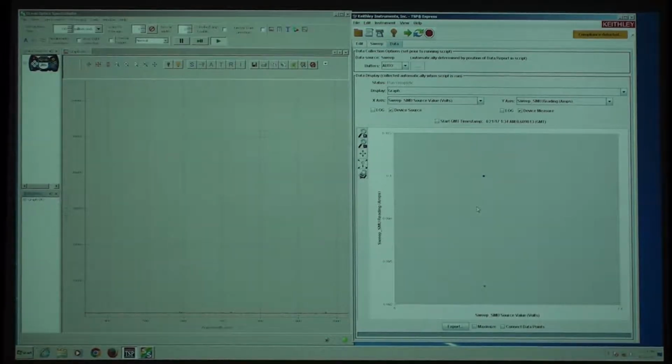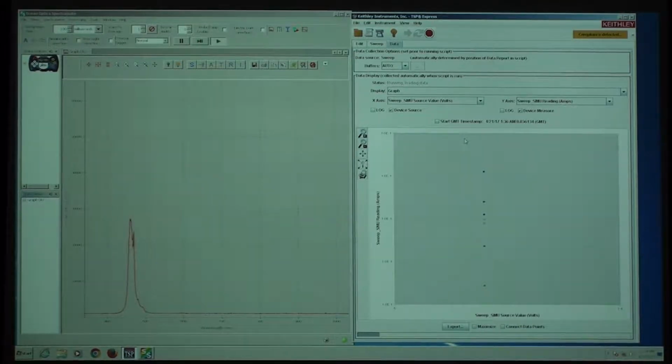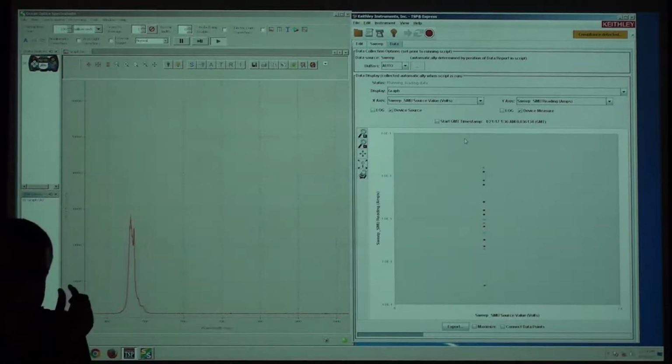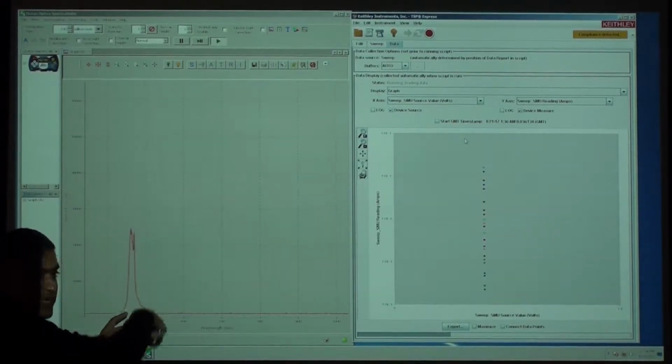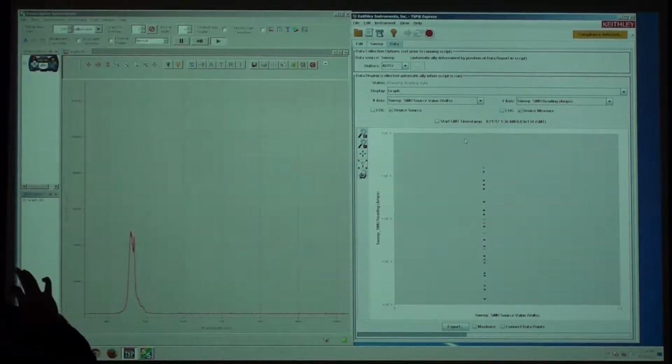Why do we see 2 peaks in the spectrum? When it was there, it was like a little drop. Good point. The quantum wells have many states in them, and you can have transitions between the ground state to valence band or the first excited state to valence band. You can see all of that in this. Or if you have quantum wells of slightly different thickness, there is one peak because of one well, the other peak for another well, because the band gaps are slightly different depending on the thicknesses. So you can design it in that way too.